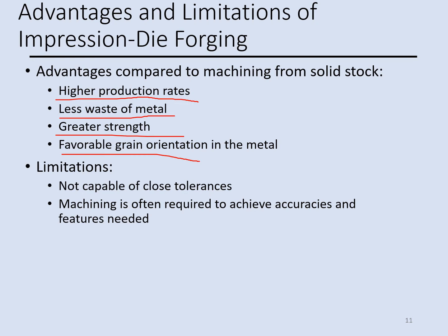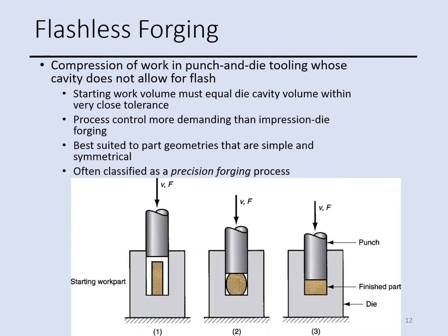Limitation, it has some limitation with the close tolerance. As I said, since we have flash in the process, in the workpiece, normally we need some machining, and the machining is required to achieve the accuracy and features that we need.